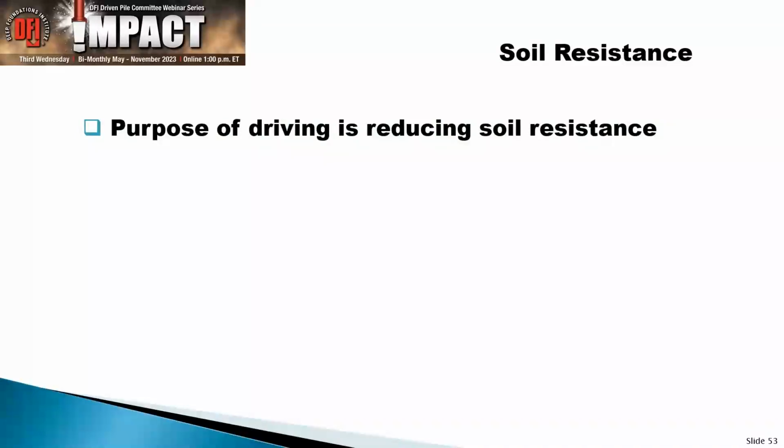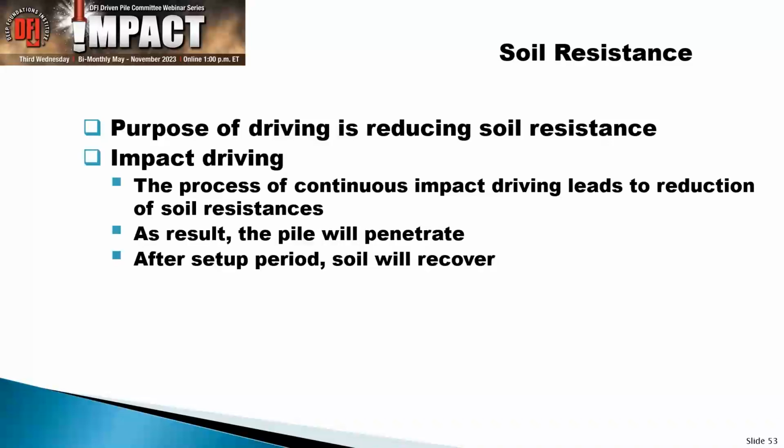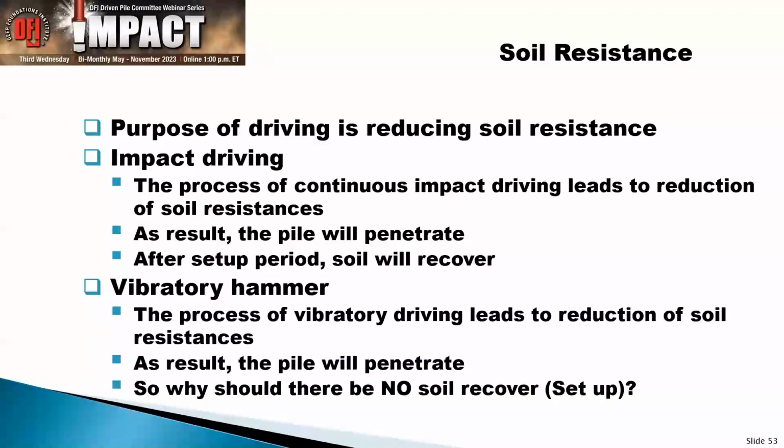Now, what happened there? Obviously, when you drive the pile into the ground, you reduce that soil resistance. And with impact driving, we know how that works. But we also know with impact driving that after you've finished your pile driving, you have soil setup. So the soil will recover somewhat.